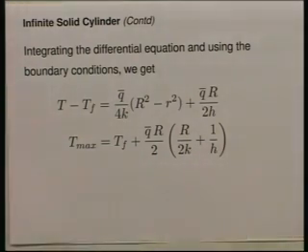So, these are two simple one dimensional problems with uniform heat generation, which we have solved for the case of an infinite slab of width 2b, and for an infinitely long solid cylinder. We could solve similar one dimensional problems also. For instance, on your own, I suggest you try to solve the problem for a long hollow cylinder, inner radius r_i, outer radius r_o, with heat being generated uniformly in it.